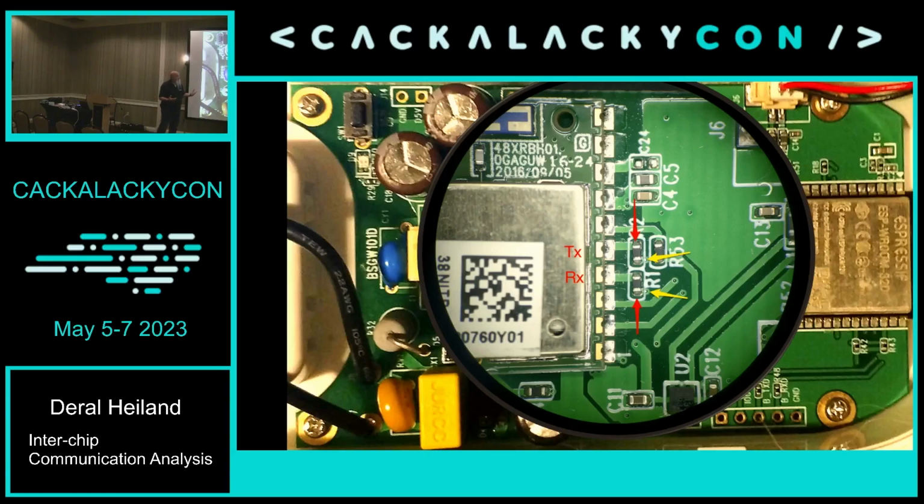because if you connect these 2 modules up directly, they won't communicate. So if we need to tap into inter-circuit communication to do this, you've got to be careful where you tap in. Since there's an impedance issue there, if you tap into the wrong side of the resistors and try to do anything weird, you'll load the circuit and actually cause communications to halt. So we found out in most of these cases, all the cases where I've encountered this, you want to tap into the transmit side of the communication.